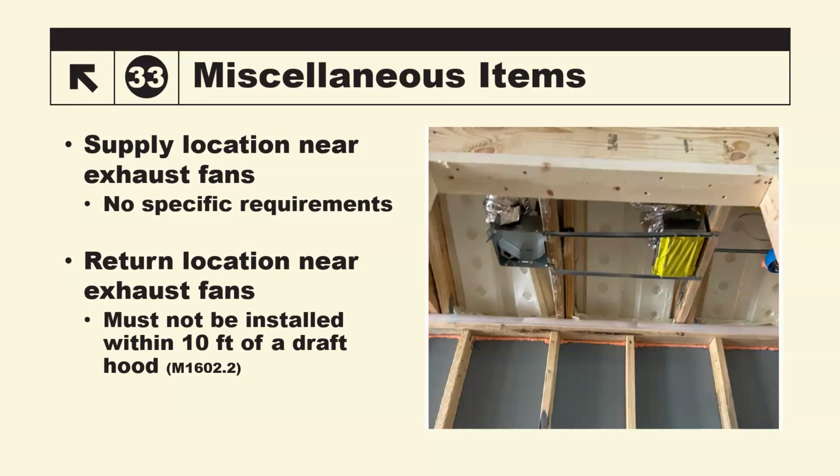And again, I'm not an HVAC technician guy. There's some encapsulated houses with foam that people are also putting returns in. In my opinion, that's not really a good idea, although those are probably sealed furnaces, 90+% furnaces that are sealed combustion and sealed venting. All you're really doing is pulling air from the attic itself, but that may not be a good idea to do.